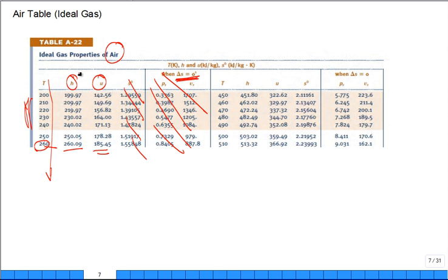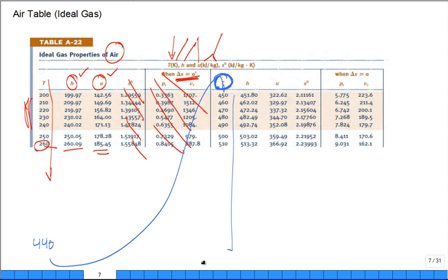But temperature, enthalpy, and internal energy are given. Notice they come up here and say the temperature is in units of Kelvin. H and U are in units of kilojoules per kilogram. Also, to save space, what did they do right here? A second whole set. So you come down and then you need to look back up, because right down here probably is 440, and then it goes to 450 and then down. Then it goes to the next page.